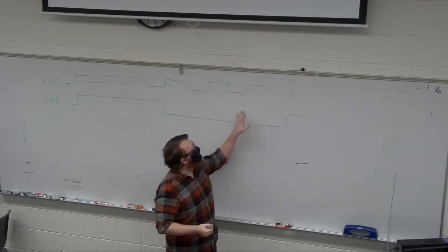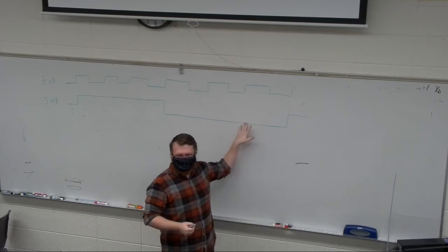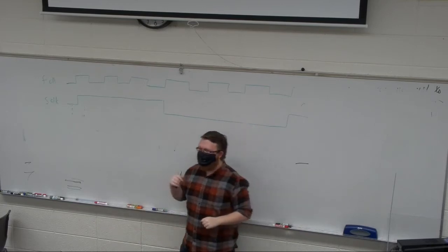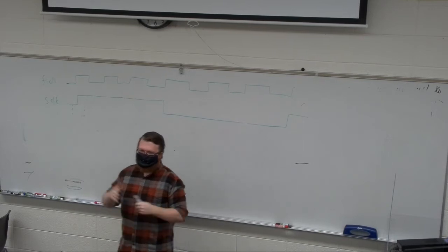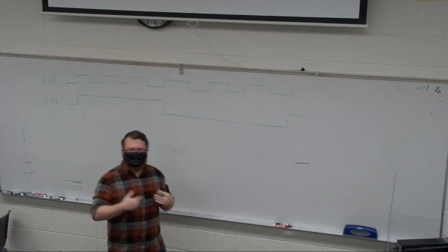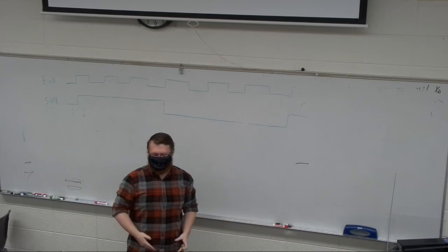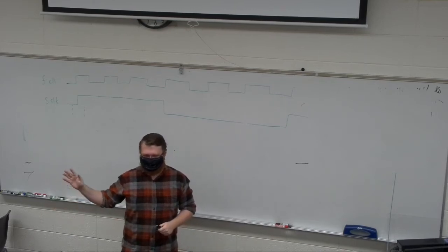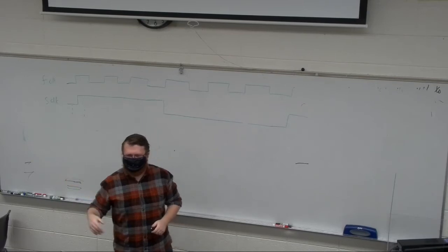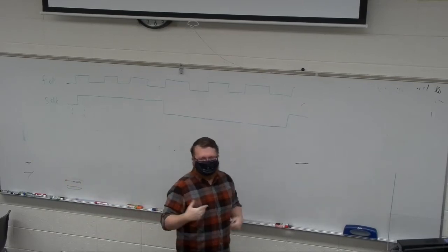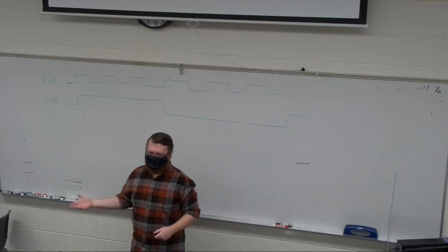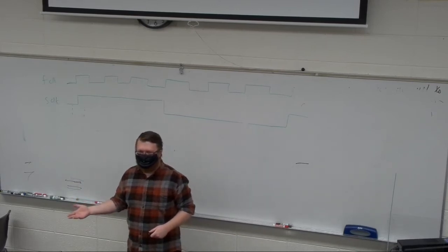Interestingly, the faster the fast clock is compared to the slow clock, the easier this gets. This gets illustrated in your UART lab, right? This is essentially crossing clock domains, because you're going from your 100 megahertz to 100 kilohertz, I forget the exact number, 115,200, right? You're crossing clock domains. You're just counting these, and you can calculate the clock drift that you have, right?